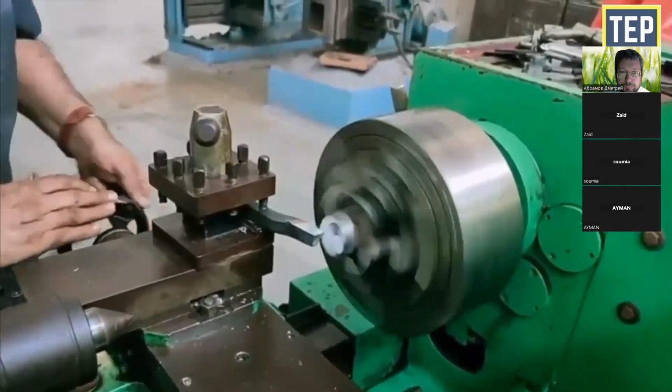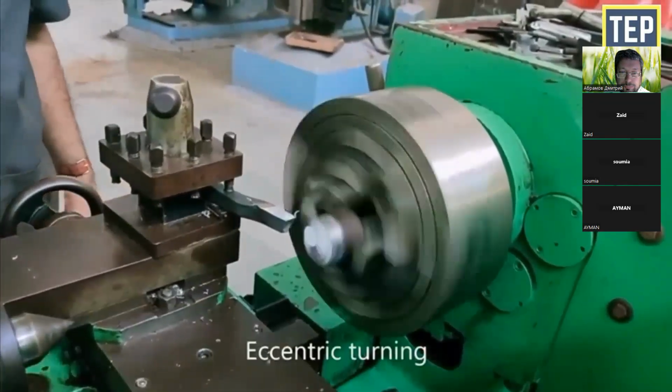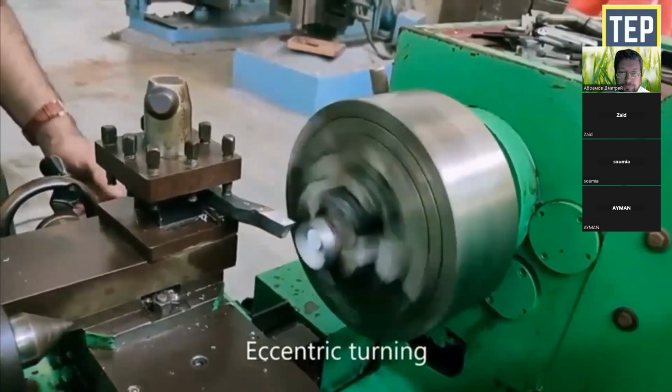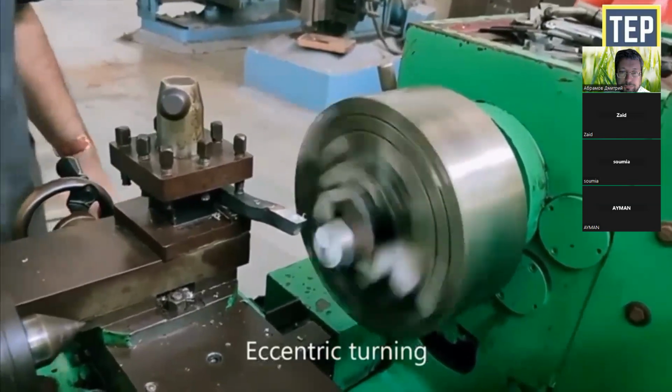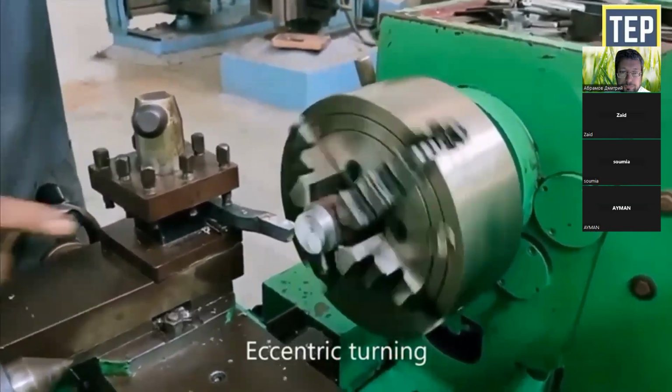Eccentric turning. When a cylindrical surface has two separate axes of rotation, with the first axis offset to the other axis, such a workpiece is machined by the operation called eccentric turning. Here 3 sets of center holes are drilled. By holding the workpiece at these 3 centers, the machining operation for each of the surfaces can be completed.